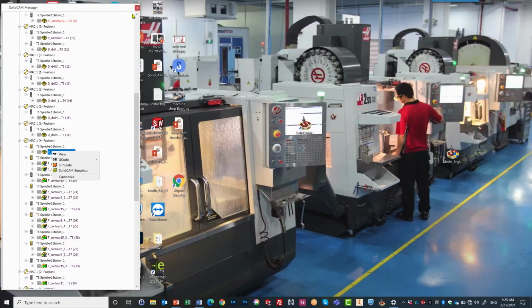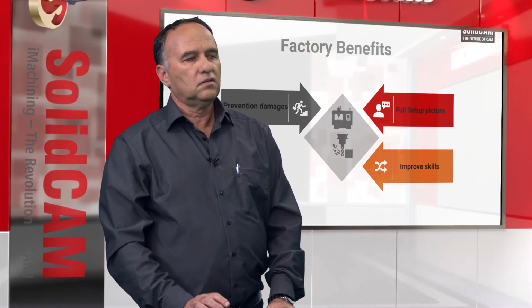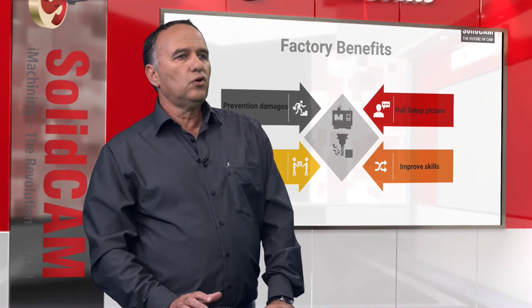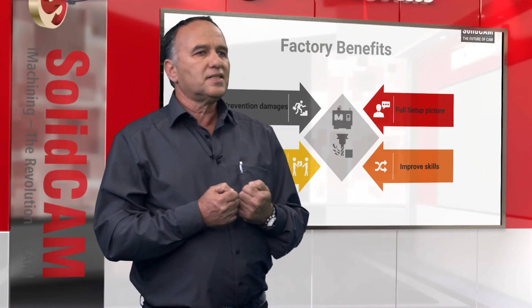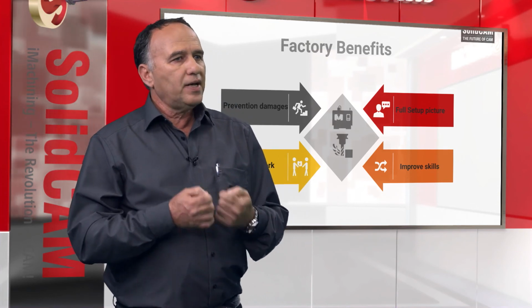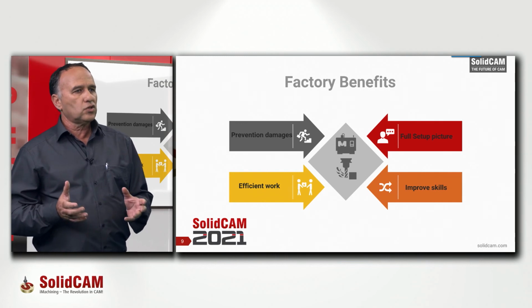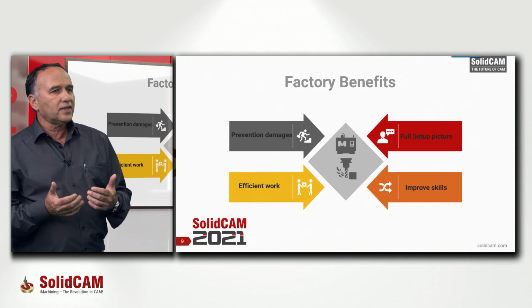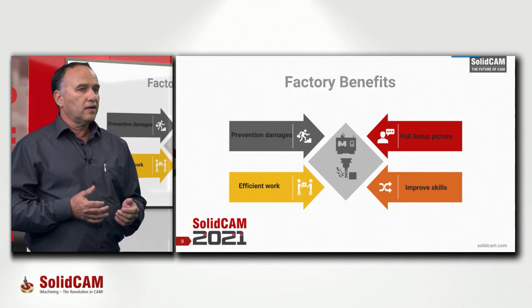Okay, great. So Zvika, could you please tell us about the machine shop's benefits working with these versions? Of course, Sidney. So there are many. Let me tell you about the major benefits. First, preventing CNC machine and tools damages. The ability of the setup operator to see full solid simulation and machine simulation inside SolidCAM gives him the confidence which prevents unexpected crashes in case of programming mistakes.